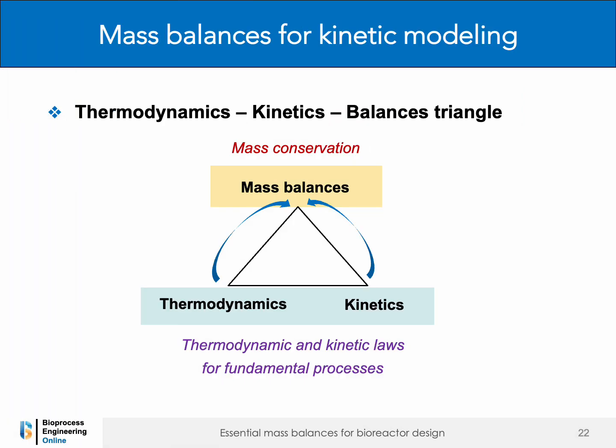Constructing a bioreactor simulation model involves deriving the mathematical relationships that describe the time-dependent variations in the concentrations of the different components in the medium. This modeling methodology follows the concept of the modeling triangle, which integrates instantaneous material balance equations, expressing the principle of mass conservation, with thermodynamic and kinetic laws describing the underlying physical and biochemical phenomena.